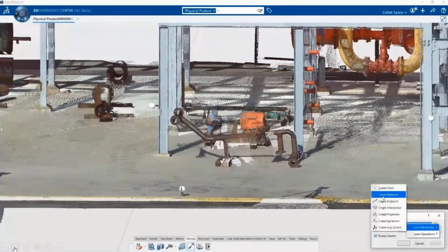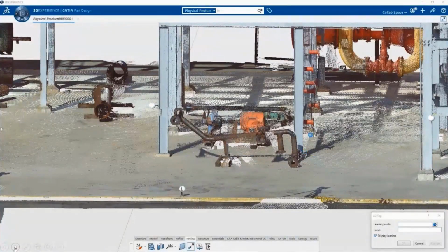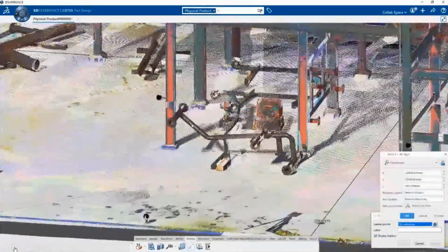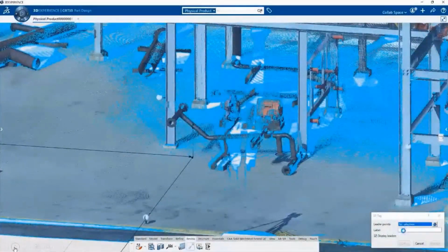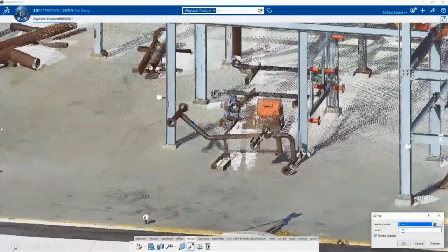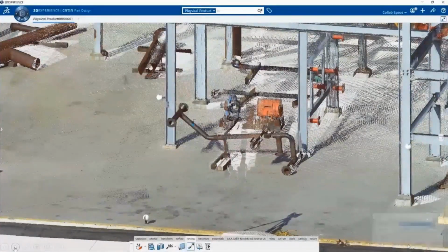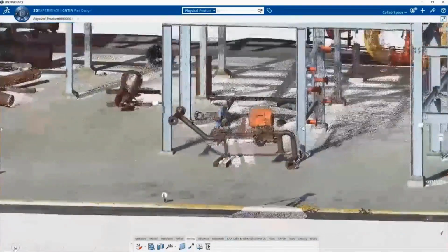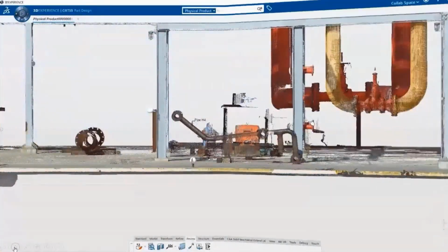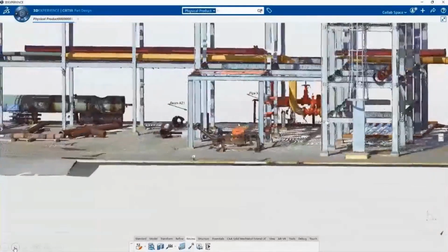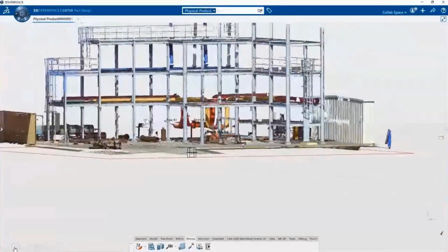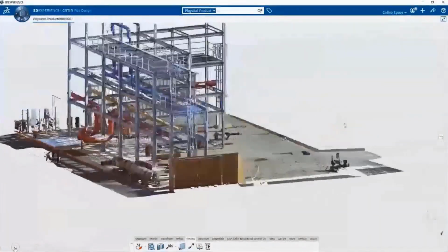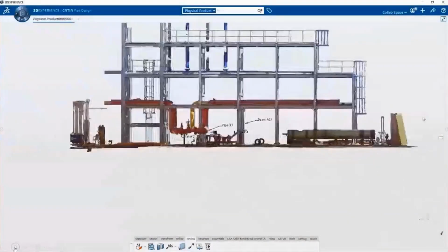So some functionalities you can use, very standard inside this navigation, is the capability to add some 3D annotations, potentially to identify equipment. Why not? And so you will set these 3D tags, and it will ease the possibility to read what is inside and understand what you are doing. Another possibility could be to slice. Make a section of your cloud of points to better see some inside area, for example.